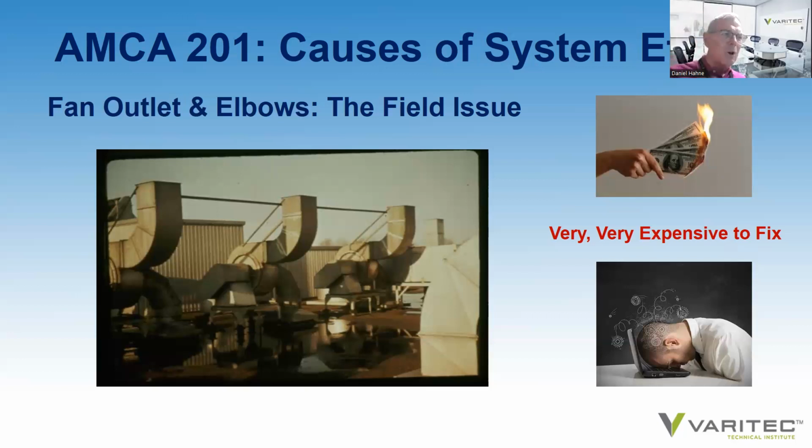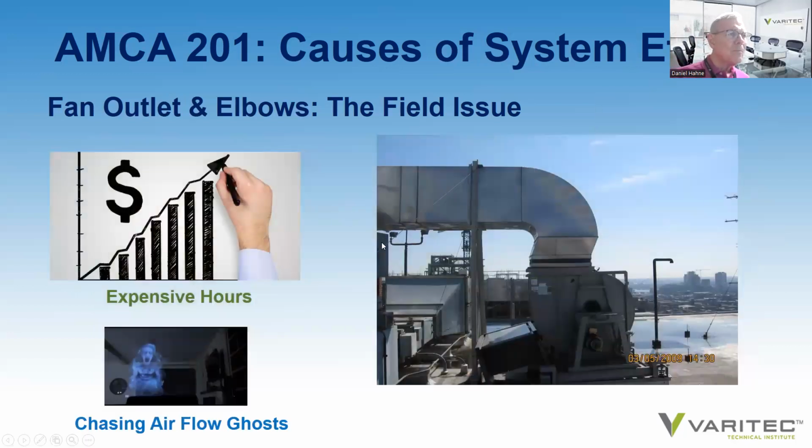Many engineers know perhaps not to design fans in this configuration, and I always recommend that coordination occur with the manufacturer, salesperson, and the contractor to make sure they're assigning the appropriate orientation to the utility vent set to prevent this condition from occurring.